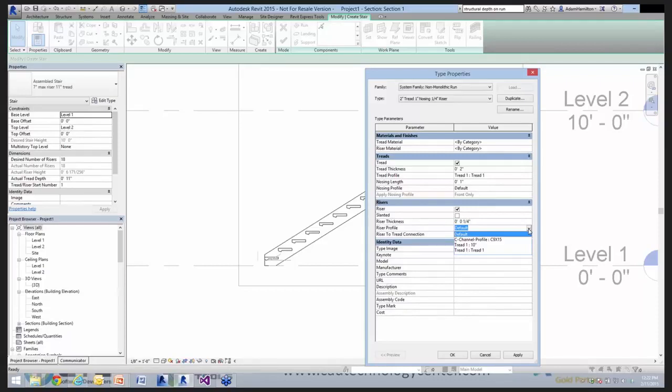So you would need to create either a new style under default with the proper thickness, or you utilize this thickness here to be, say, 1.5 inches, or if you're using any other size or shape, to be able to load that in. Now, I've looked at a couple manufacturer websites regarding stair pans. So if you search up steel pans, there's quite a few.